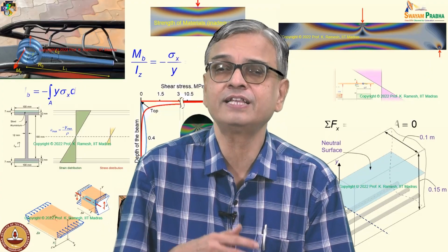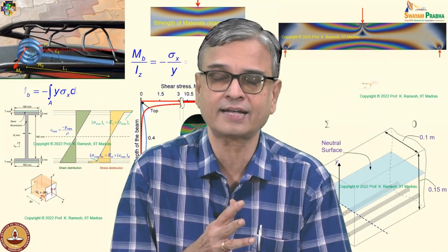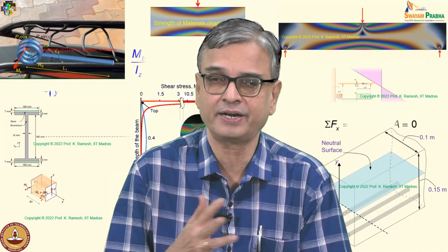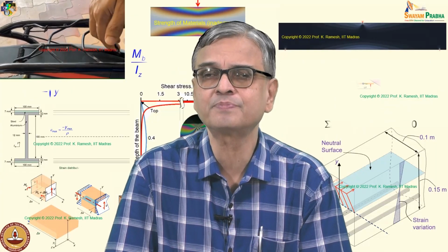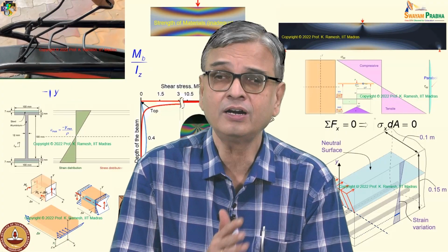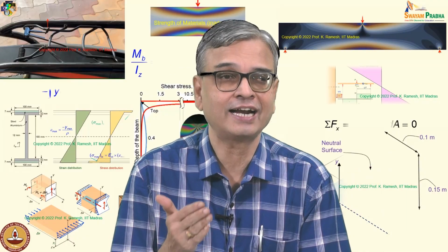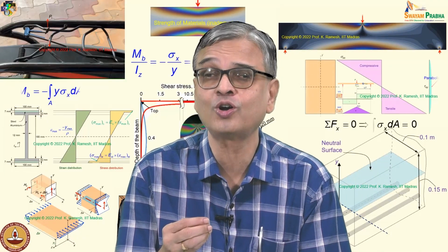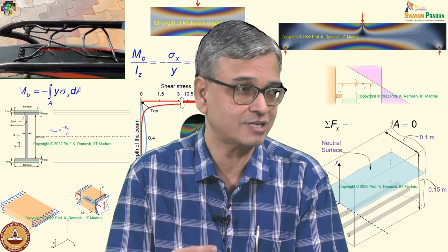And we have also seen, if you have an unsymmetrical cross section subjected to even bending in one axis, it has unsymmetrical bending. Then we have also looked at the problem of a simple torsional spring in your cycle. We have learned that it actually transmits a bending load, and at this level of the course you do not know how to handle a curved beam to start with.